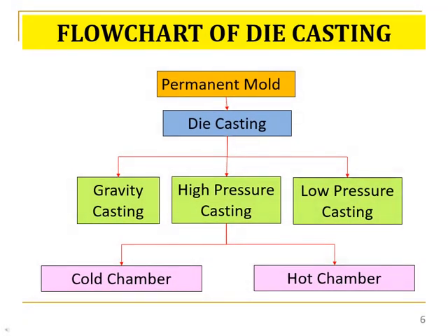There are really several distinct processes included under the general name of die casting. The die casting process actually has 3 main sub-processes, where the 3 processes differ mainly in the amount of pressure. These processes are, 1. Permanent mold casting, also called gravity die casting, 2. Low-pressure die casting, and 3. High-pressure die casting. Normally, the term die casting is used to mean high-pressure die casting, but the general term embraces all 3 subcategories. Cold chamber and hot chamber are the processes placed under high-pressure die casting.